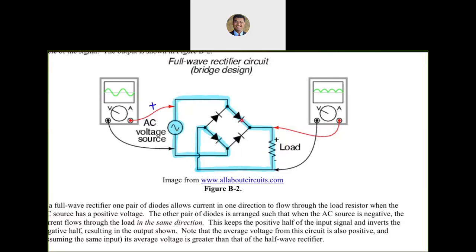There are two diodes that are being used in forward biased region. Each of them requires 0.7 volts to turn on. In total, that is going to be 1.4 volts to turn on, meaning the remaining voltage will go across the load. So Vs minus 1.4 will go across the load for the positive half cycles.